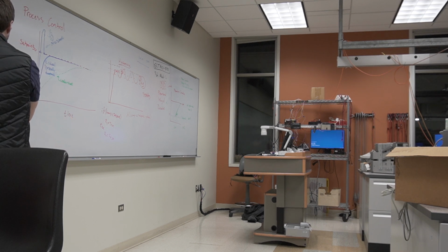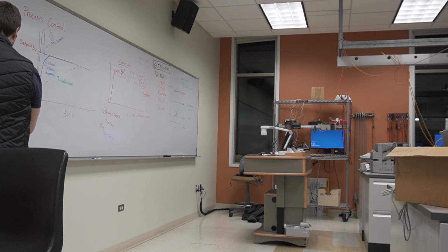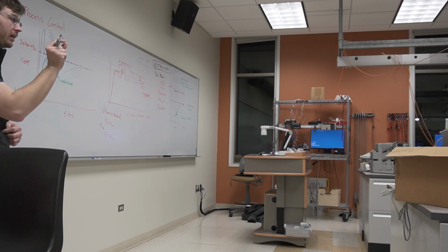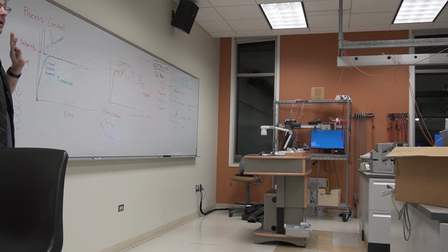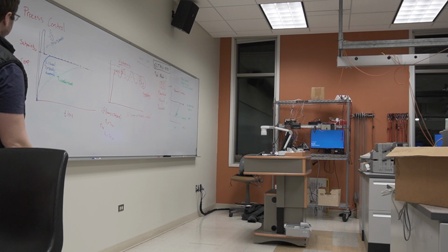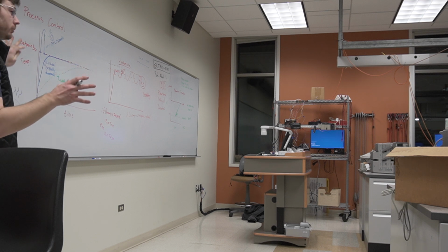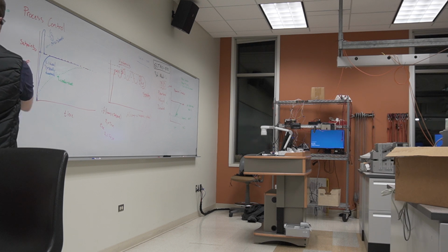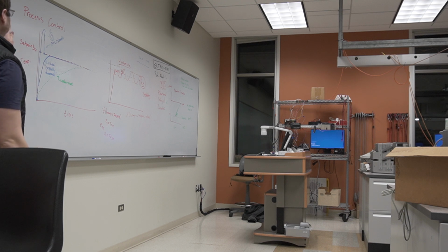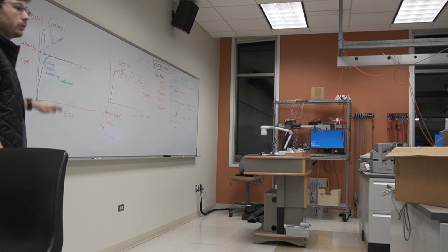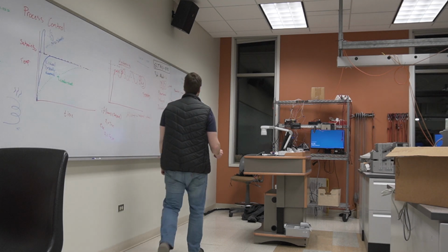What that means for our tilt system is, if we tilt this way, our controller says we should tilt back. The end result is that it's almost tilted upright. It's off by just a little bit, but it always will be off by that little bit because it's always responding proportionally to what it's seeing. Unless you have additional sensing, or rather a better controller, to nudge that back into range to account for this 0.02 error, it will always have some amount of error in it, okay? But proportional controllers are great for a lot of things.